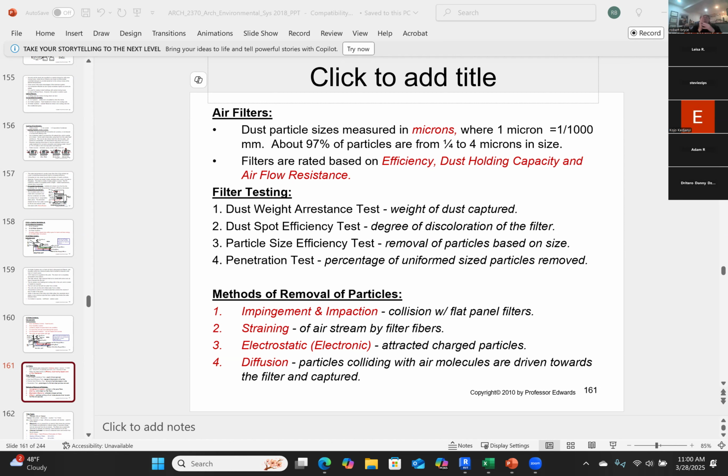And you know that if you have a wide open hole in the wall and you're trying to blow air through it, there's not going to be as much resistance as if you put a very fine filter or screen across there and then try to blow air across it. You know, there's a resistance there. That resistance has to be overcome by increasing the flow of air, which we know translates into additional costs because we're using more energy.